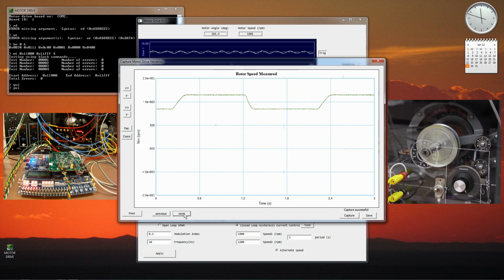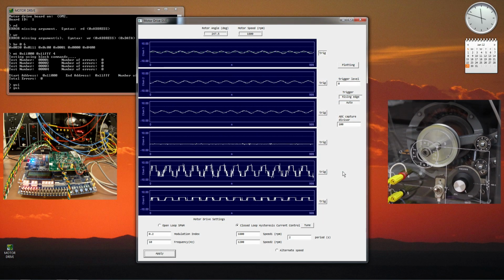Okay, so that looks quite a bit cleaner. It actually looks a little bit faster, very slightly, but the overshoot and undershoot is completely gone. Alright, so I would say that's tuned about as good as it's going to get. Let's take a look at the smoother one. So you can see that's probably pretty close to critically damped. That's pretty good performance.